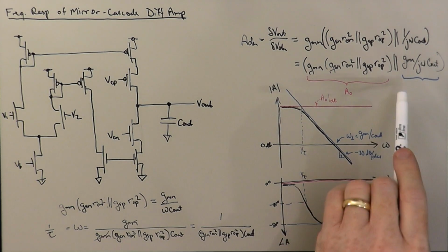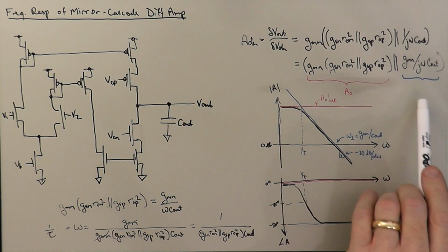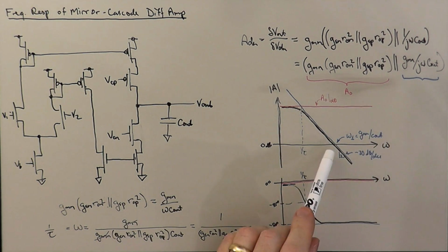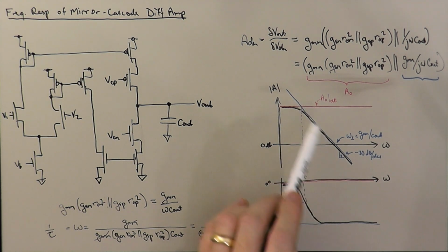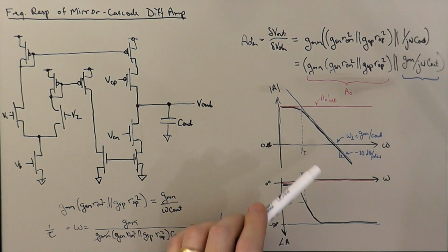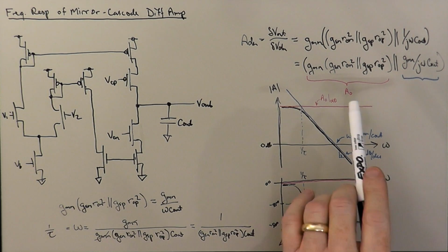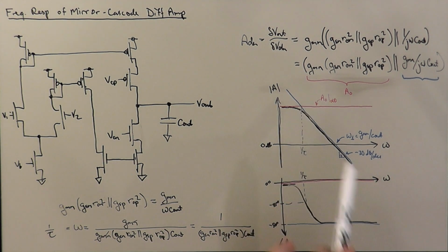If you have a parallel combination, you can basically deal with the components of the parallel combination by plotting them separately on the Bode plot, recognizing that we have a double log scale here, and so very rapidly, if one curve is above another curve, it becomes much larger very quickly. And so we have this way of dealing with these things and finding where the pole frequencies are, where the zero frequencies are, just by setting the magnitudes of these things equal to each other to find out where the crossing points are. Okay.